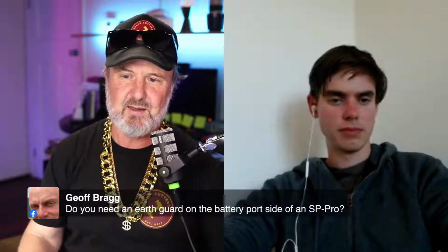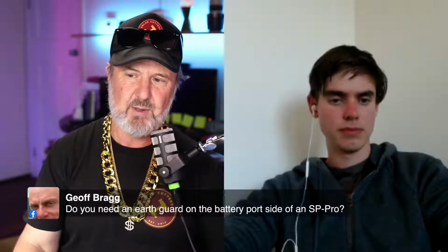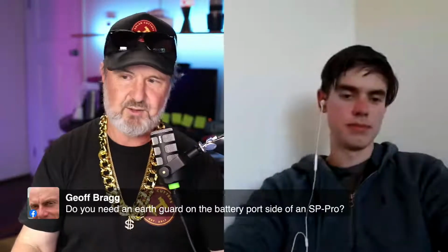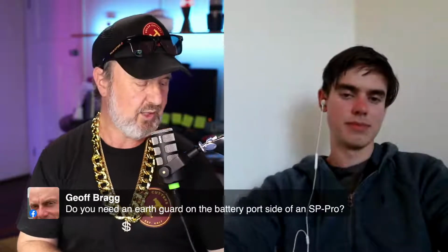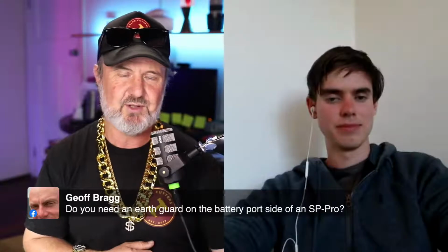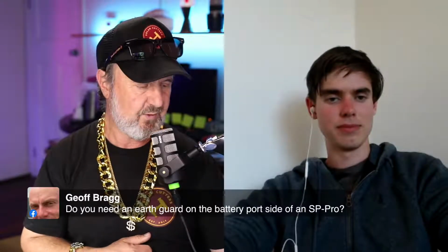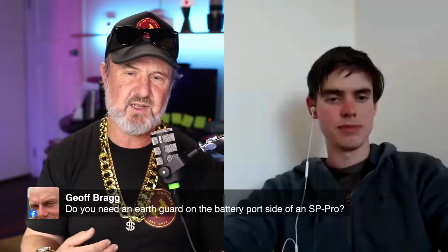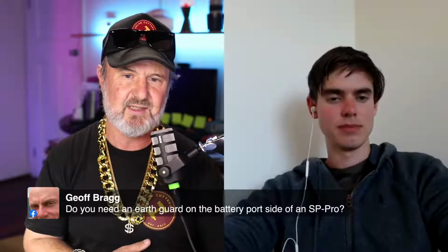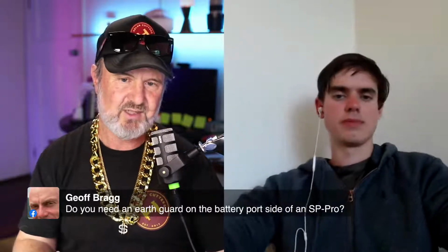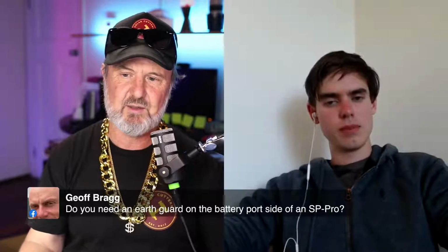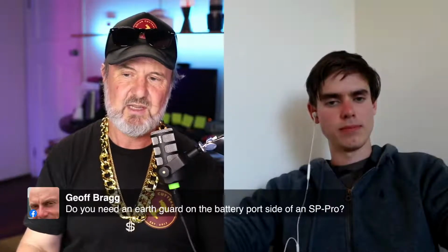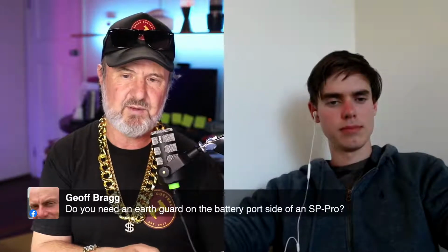Jeff's asking, do you need an EarthGuard on the battery port side of an SP Pro? I think I can answer this one, Jeff. It depends on the voltage of the battery. If the battery is above 60 volts for more than 0.2 of a second, under any operating conditions, yes, you do need earth fault detection on that system if it's not galvanically isolated from the PV array.